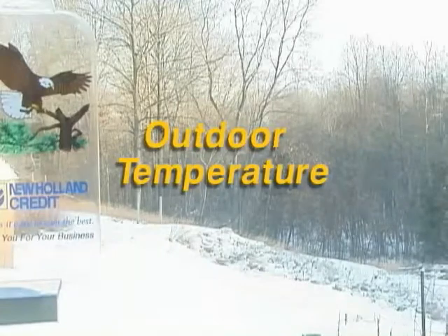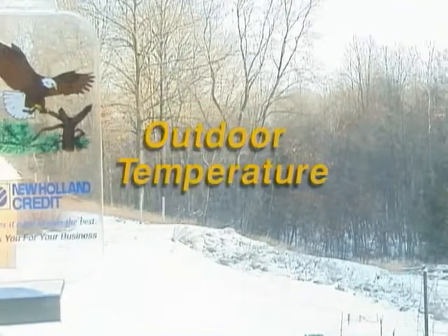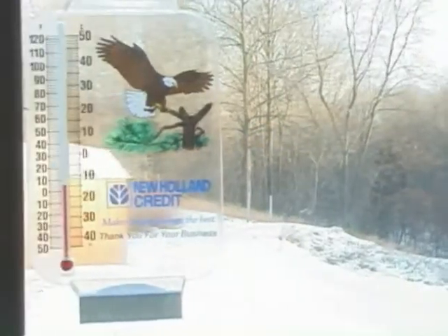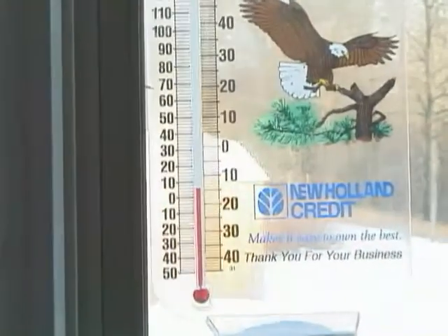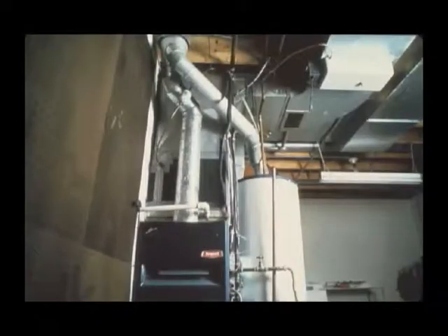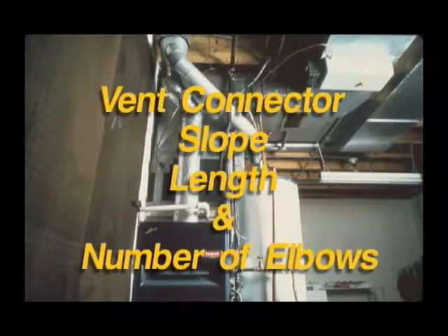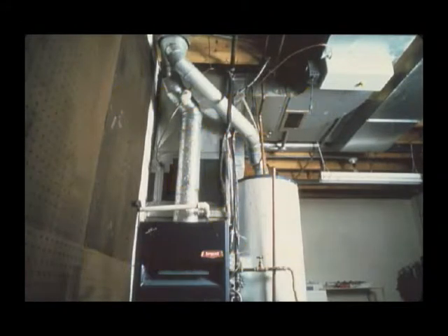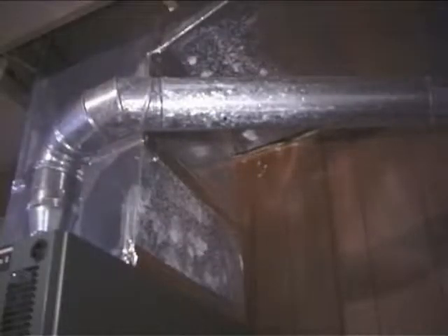Outdoor temperature. The colder it is outside, the stronger the draft will be. Conversely, the warmer it is outside, the weaker the draft will be. Vent connector slope, length, and number of elbows. Friction in the venting system reduces draft.